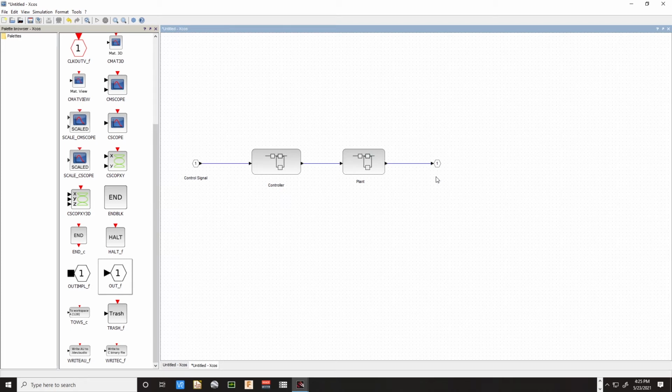So this is the output of the plant, or whatever the plant is doing. The plant is turning on, so this is just the output. And if this were an air conditioning system, this would be your house cooling down. The plant would turn on the air conditioner or turn on the heater, and it would cool off or heat up the house. That's the output. In this form, this is what we call an open loop system. There's no feedback.